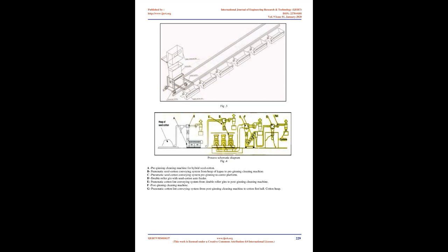In India, the majority of ginning and pressing units have a standard setup of 18 to 24 ginning machines installed in 2 rows in the ginning hall. Manually, seed cotton is loaded to the feeder of each gin. The feeders feed cotton to the gin uniformly at a controlled rate. 3. Ginned cotton after ginning is conveyed to lint cleaners.